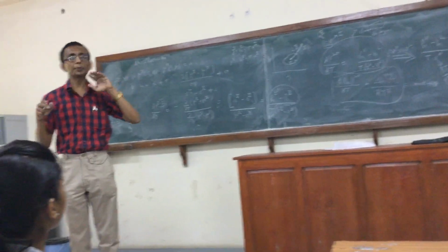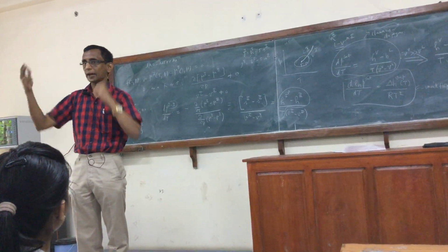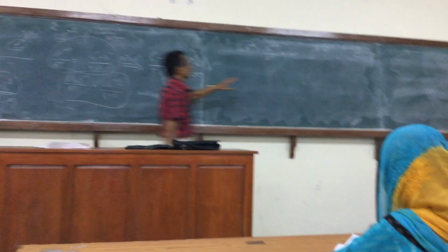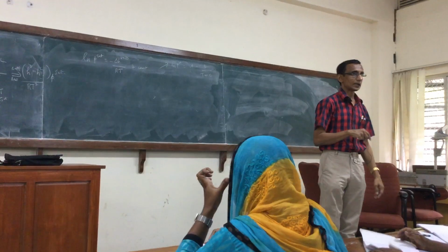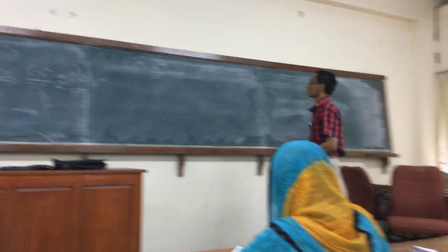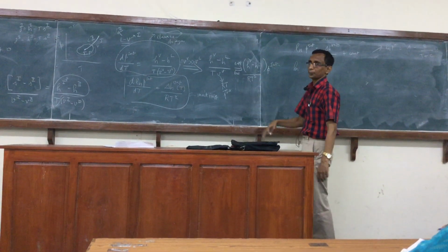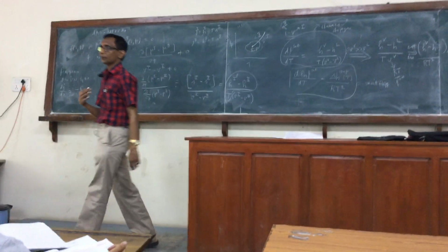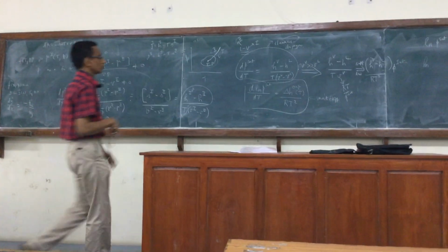It doesn't have to be A, B and C; it's just that they are fitted to the experimental data and tabulated. So rather than give the whole table, you just have the constants A, B and C for various substances and you will calculate the saturation pressure. This is a slightly different approach. This is more fundamental than the Antoine equation, but you can clearly see the form of the Antoine equation is chosen possibly based on the integrated form of the Clausius-Clapeyron equation.